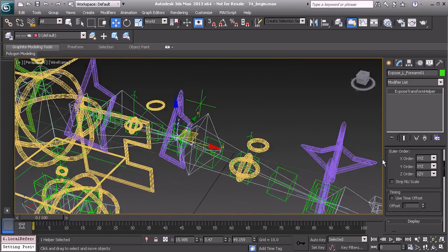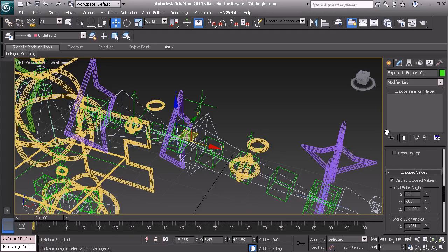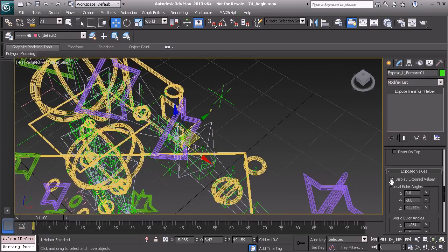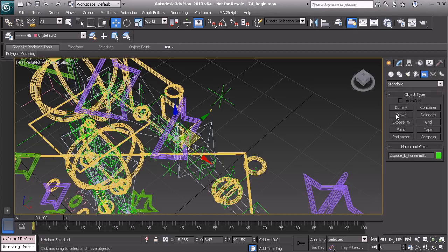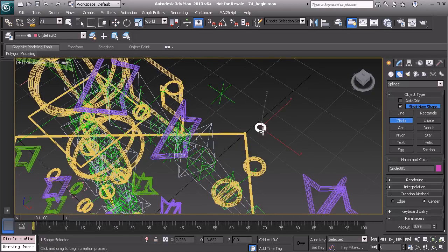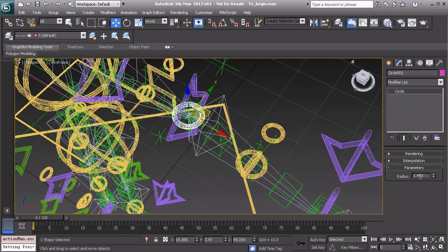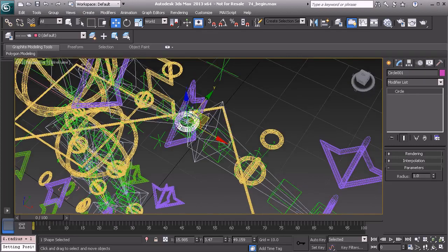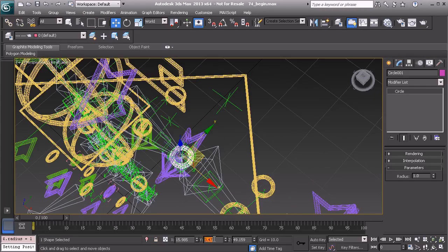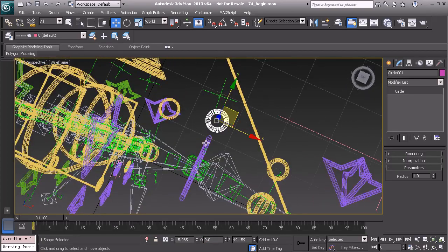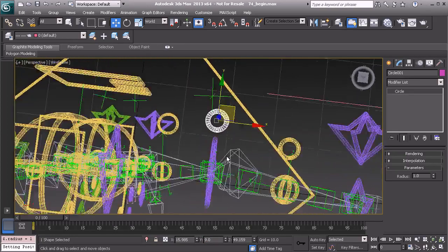Alright. So once we're good to go here, we can take a look at our rotation. That's going to work out just fine. Let's now start to set up our bend control. So we'll create a circle. From there, we'll quick align this over to the forearm. Let's make sure we set the radius to 1. In world mode, we can move this out, let's say to about a value of 9 in the Y. That way it doesn't intersect with the elbow control.